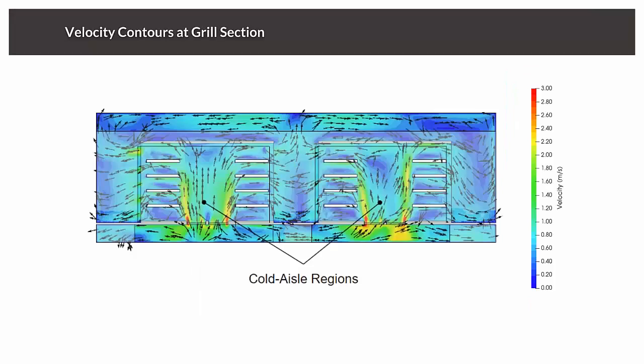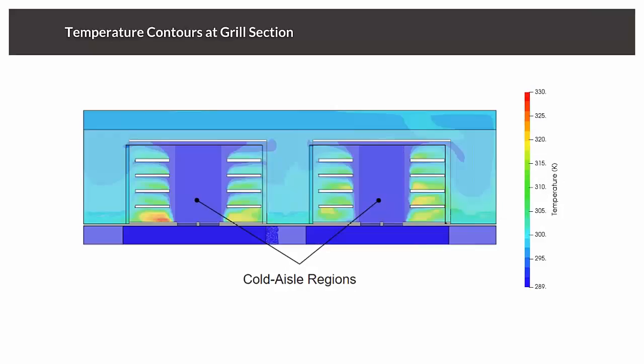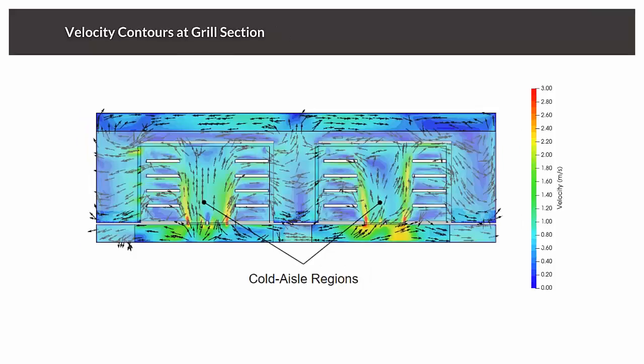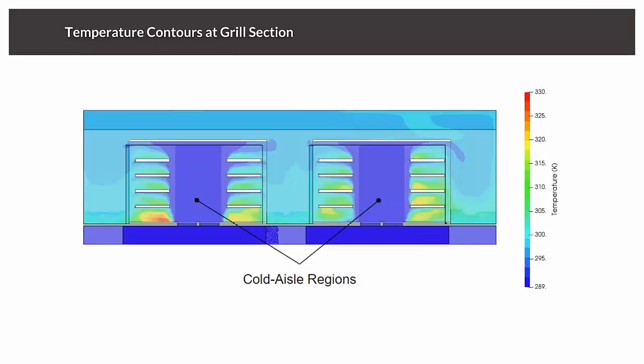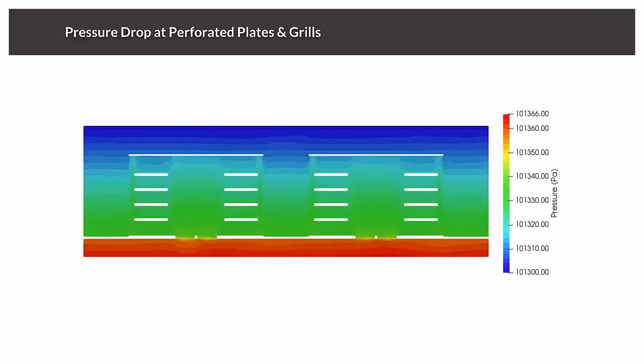and some side cuts to visualize the cold aisle regions where we have air being pushed into the aisle from the plenum and distributed through the servers themselves. This shows the heat generation and the introduction of heat into the air as it is blown. Notice the interesting effect that because we are pushing the air from the plenum with this big jet effect, the bottom servers are subject to worse cooling, and they might get higher temperatures.